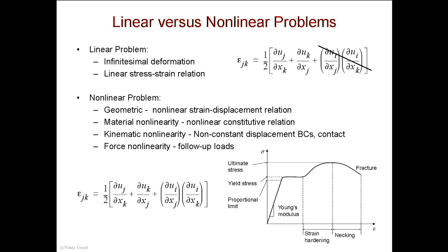Another thing you can do: you think the stress-strain curve looks like this, but you want to run the model without doing the nonlinear analysis. I could just run it linearly, and if the stresses at the stress concentration at the hole are not higher than the ultimate, it's probably conservative. It's probably enough for you to stop there.